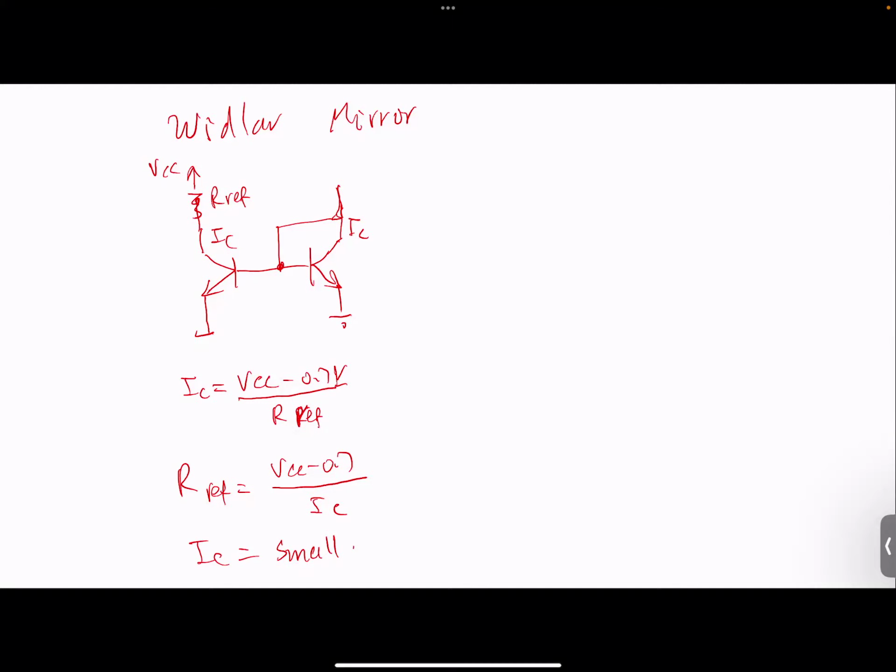One million times 1 milliamp. So 1 million is 10 to the 6, and 1 milliamp is 10 to the minus 3. So you have 10 to the 3 amps of current. For that kind of chip, you want to flow 1,000 amps of current? That's not feasible. It's not likely.